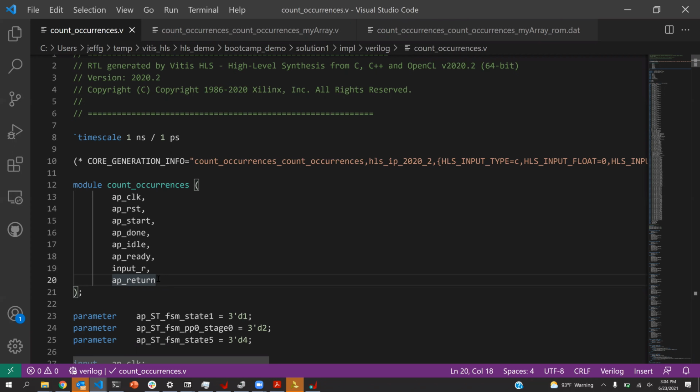It had registers, right? Like in 330, there was a register space. At the base address plus 0 is the data register, and the base address plus 4 is the tri-state register. The way the processor talked to it was not by just setting hardware wires, but through this whole bus protocol where it could read and write to different registers.